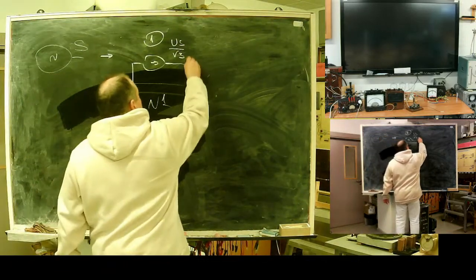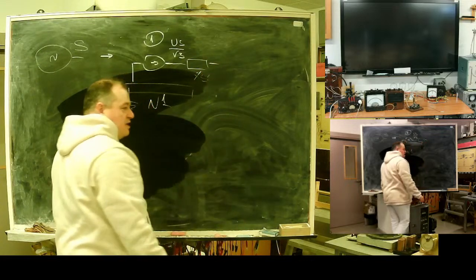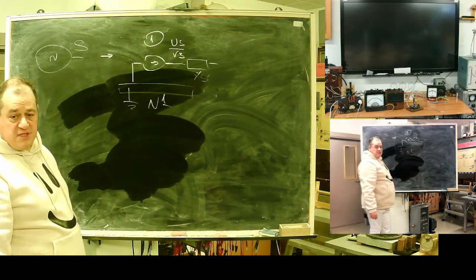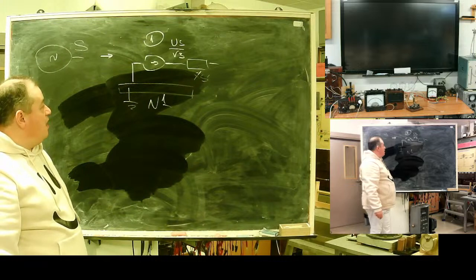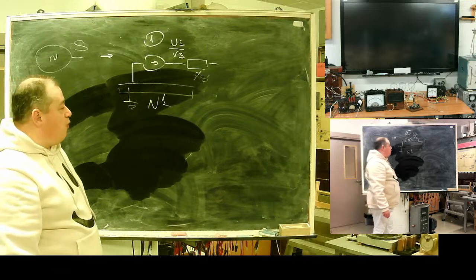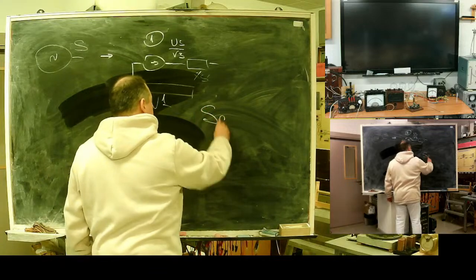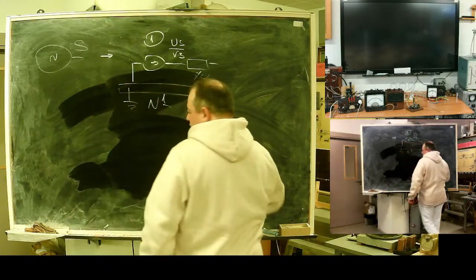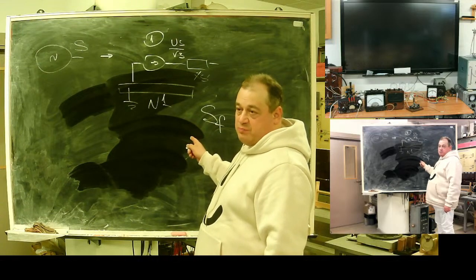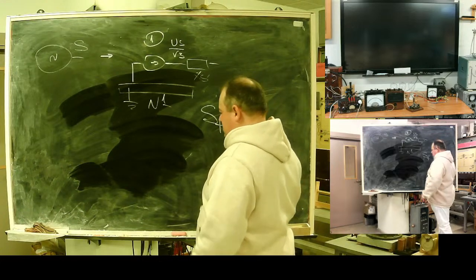There may be a system. Usually only the reactive part is accounted for, but see, it can have system resistance. Your neighbor can supply it to you, or you can have it in the form of fault power. It's the power that will be supplied to the point of fault in case of a three-phase fault.